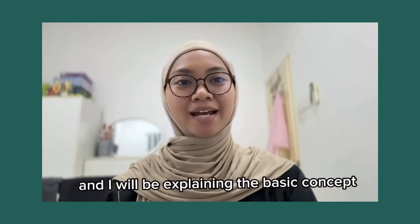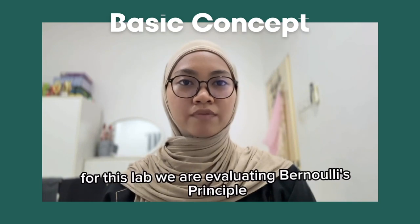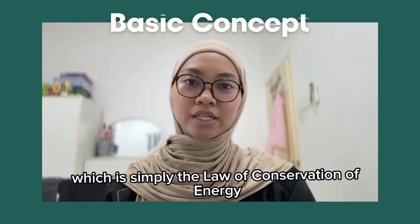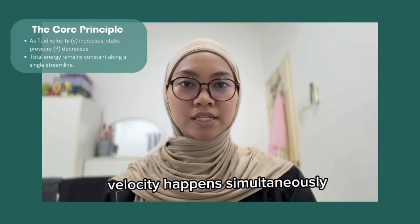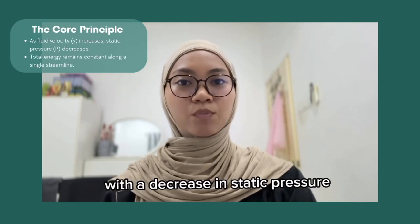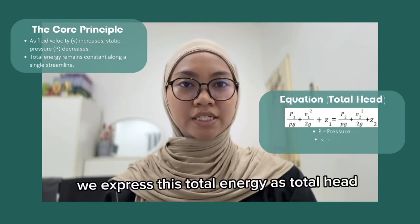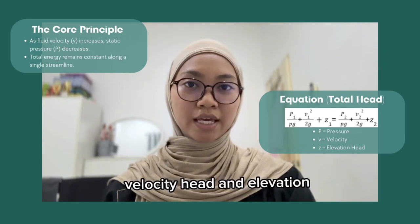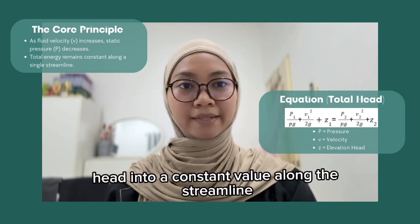Hi, my name is Alia and I will be explaining the basic concept. For this lab, we are evaluating Bernoulli principle, which is simply the law of conservation of energy applied to flowing fluid. It states that an increase in fluid velocity happens simultaneously with a decrease in static pressure. Mathematically, we express this total energy as total head, which combines pressure head, velocity head, and elevation head into a constant value along the streamline.